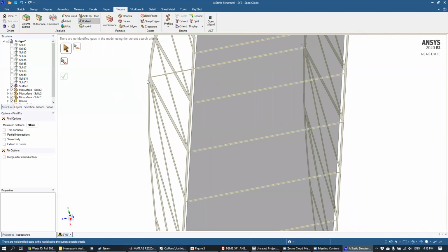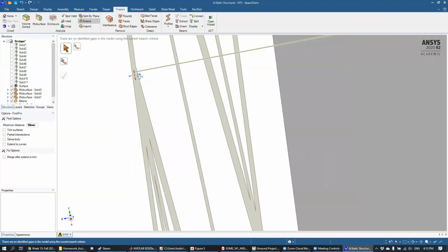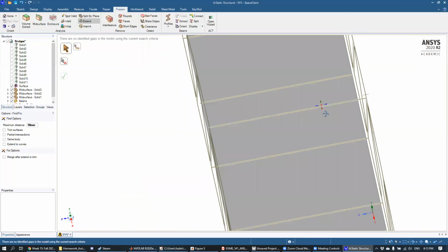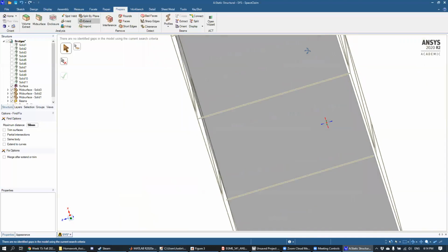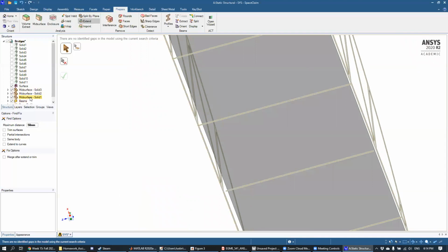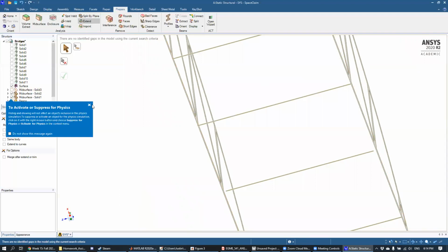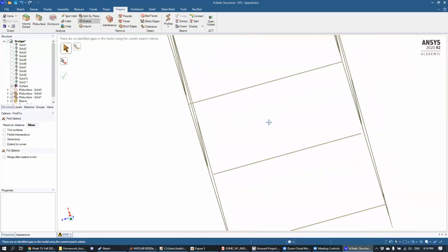Once I did that, you can see that this beam now extends all the way to the shell element right here. That's all well and good, but you can see that it didn't work for all of them. Let's go from the bottom up, and let me turn off this surface just so you can see better. You can use this menu to turn off the visibility. All I did was turn off the rod. It's still there; I just made it invisible for now.